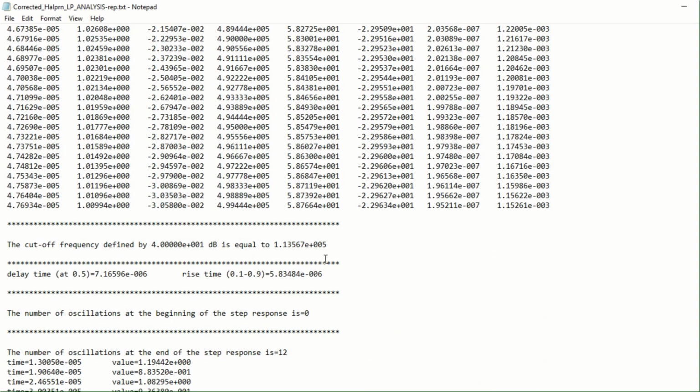And it says that the transition region is only 13% of the passband, while we were asking for 30%. So that means that we may go with a lower number of transmission zeros, or with a lower order of the filter, for example, 8th order of the filter.